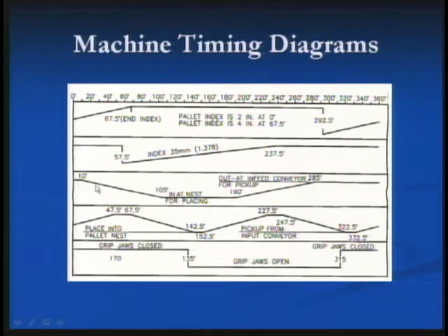The thing I'm interested in most is the assembly motions or other kinds of motions that are being created on the machine with the cam systems. This represents one of them. You see a dwell at a high position for about 10 degrees, a fall to 105 degrees. It says it's now in at the nest for placing a part. It stays there until 190 degrees. It comes back out at 285 and dwells at the out position. So this would be a double dwell type motion as described in your book. Even though it looks like there are 3 dwells, this is just the tail end of this same high dwell over here. So it's dwell, fall, dwell, rise, back onto the dwell.